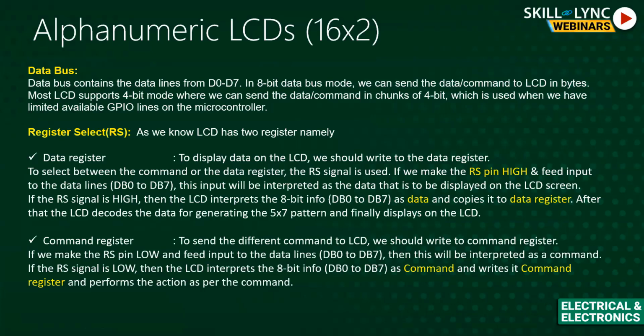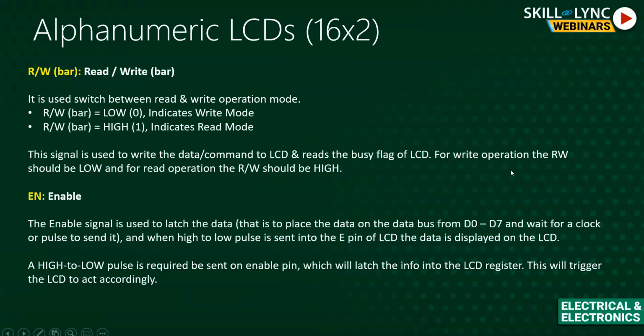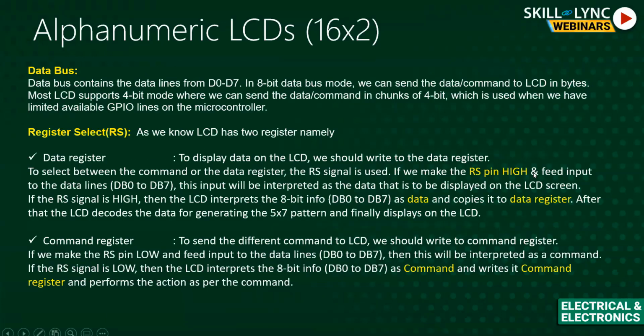To select the data register or the command register, if we make the RS pin high, it selects the data register, and if I make the RS line low, it selects the command register.